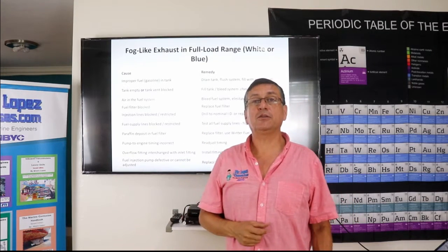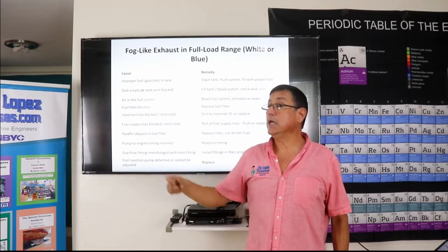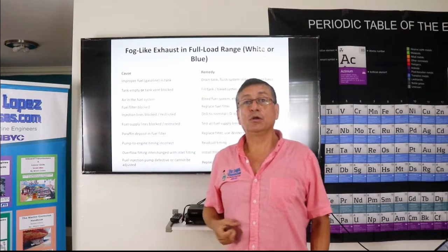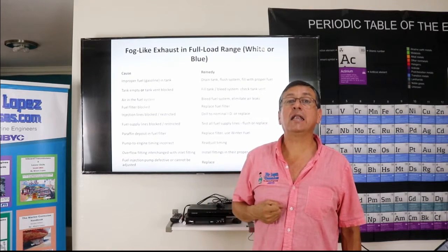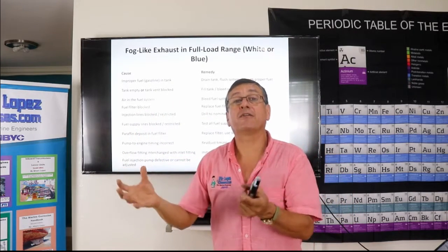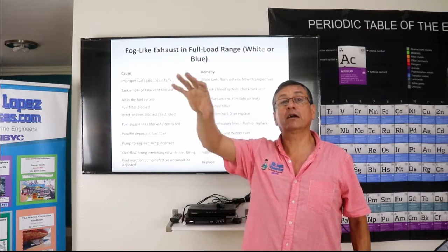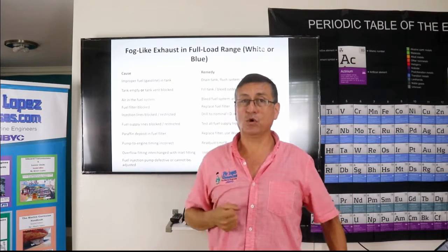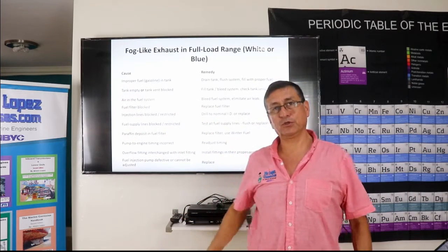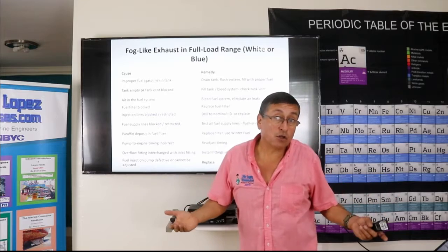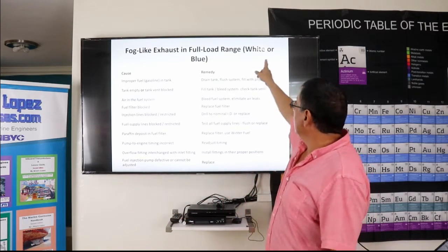Other possibility is that somebody cleaned the engine room of the boat with high pressure water and did not protect the air filters properly, and now the air filters are soaked with fresh water. When the engine starts, it sucks in water and that water enters the combustion chamber. Yeah, this is another possibility. Okay, blue smoke.